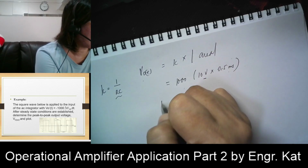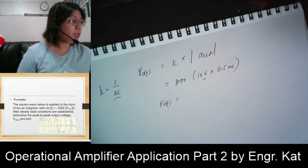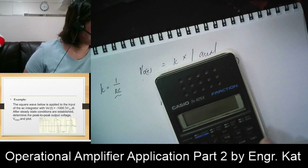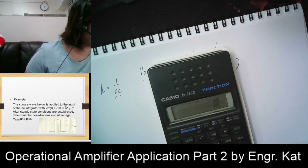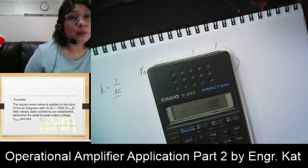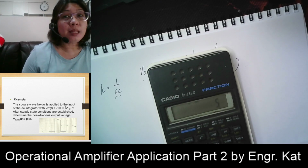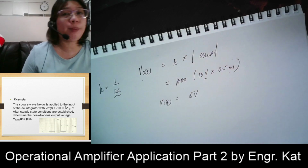So computing for this, our output peak-to-peak voltage is equivalent to 10 multiplied by 0.5 millisecond, multiplied by the scalar, which is 1000, and that is equivalent to 5 volts. Okay, so that is your peak-to-peak value.